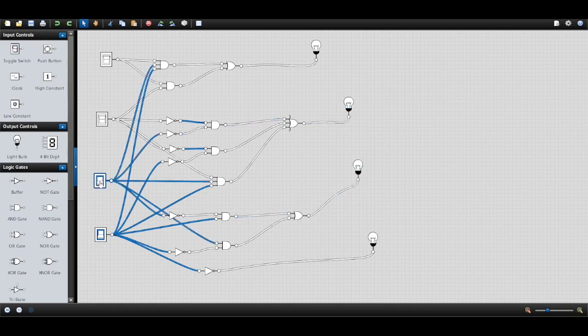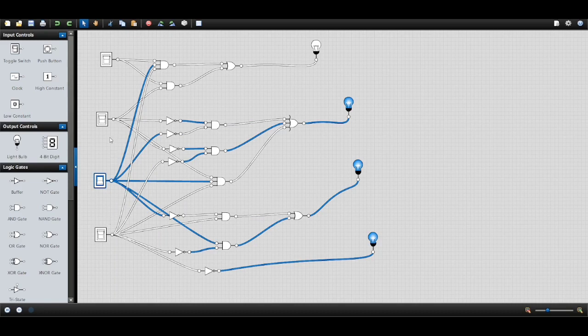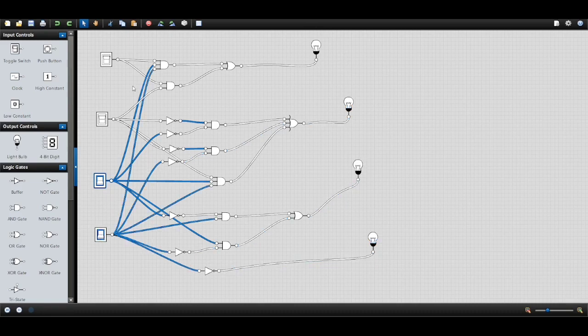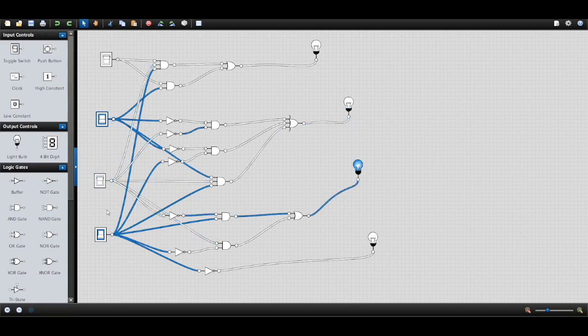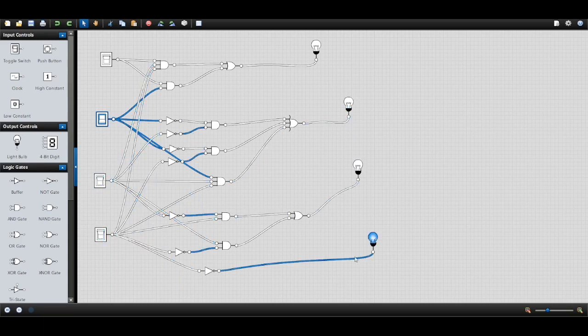If Y equal to 1 and Z equal to 0 and the other two inputs also 0, the output will be B, C and D, which is B, C and D equal to 1. The last output, that is A, is equal to 0. If Y and Z equal to 1 and the other two inputs are 0, the output will also be 0. If X is equal to 1 and the other three inputs are 0, the output will be 1 in D. D is equal to 1 and the other three outputs will be 0.